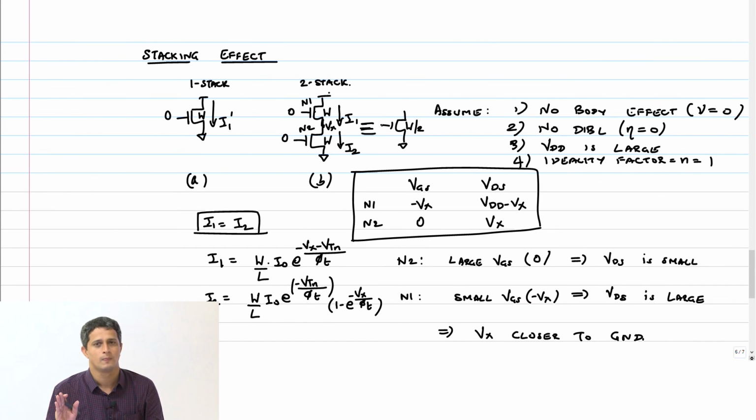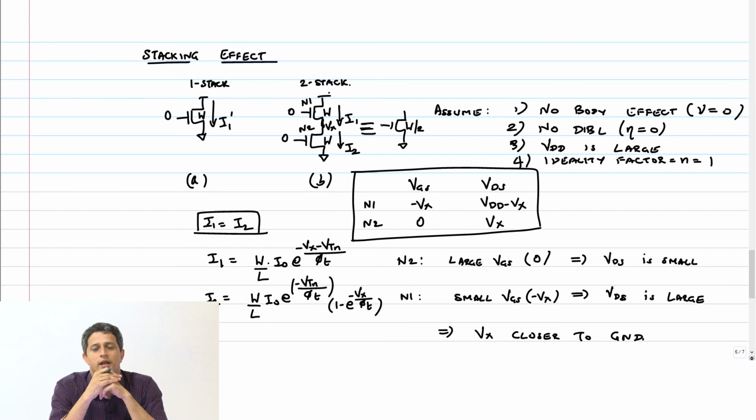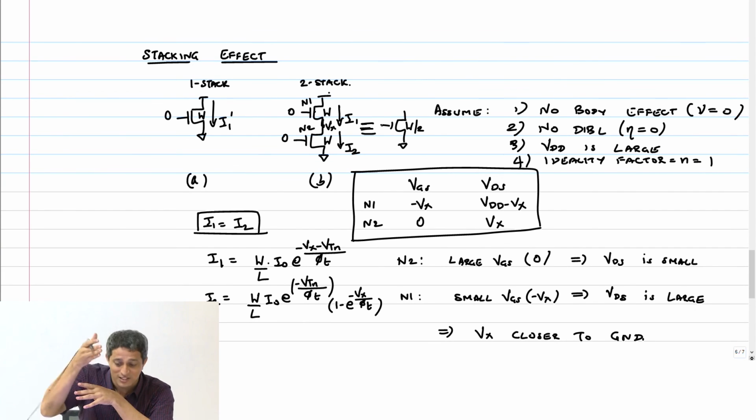It's not beneficial. What happens is, because of short channel effects, for example, now consider DIBL. For the bottom transistor, Vx is very close to 0, so the DIBL effect is extremely small there. For the top transistor, VDD minus Vx is going to be very high, close to VDD. So what will happen to the threshold voltage of that transistor? Yes, it will reduce, correct? These two fighting will actually cause a significant reduction compared to just having that VDD.